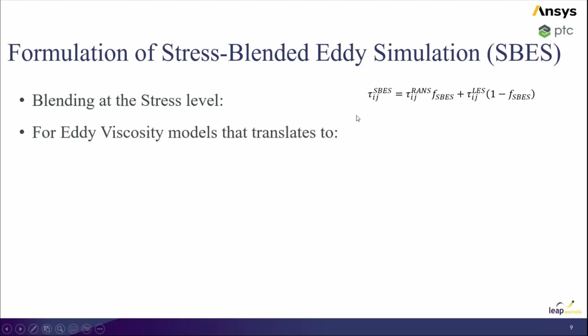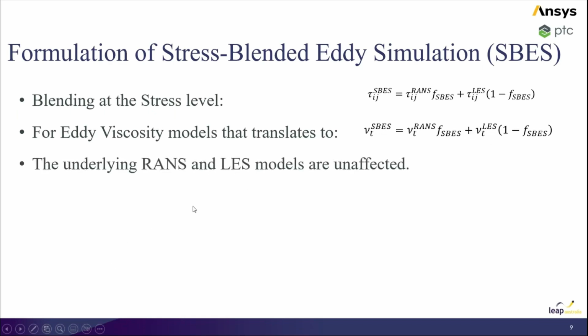But if we then think about this as an eddy viscosity type model, then we can get rid of the stress and replace that by a viscosity. And so this is our turbulent viscosity, this is our subgrid scale viscous term, essentially the damping there, that's representing that damping effect.